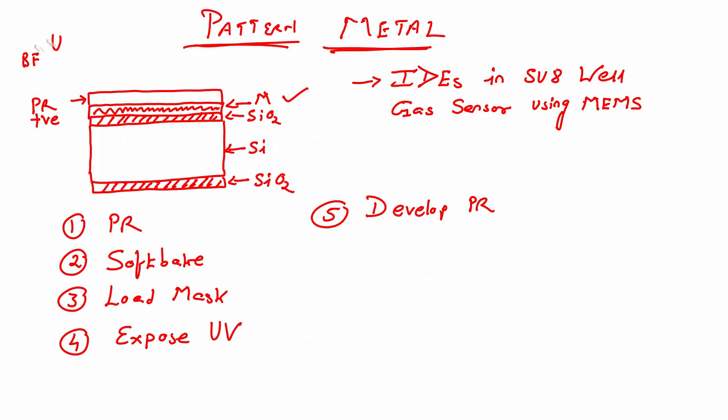I will see that the photoresist in the area that was not exposed will be there, and the area which was exposed by UV light, which is this one or this one or this one, the photoresist will get developed. So, now you know that you have this photoresist. Now, what is the next step? We want to etch the metal, because the idea is to pattern the metal.